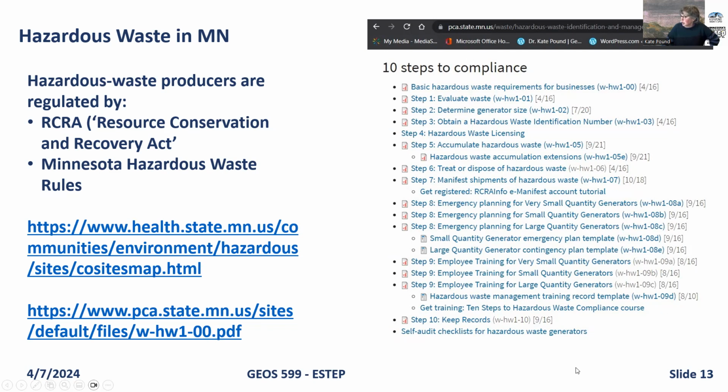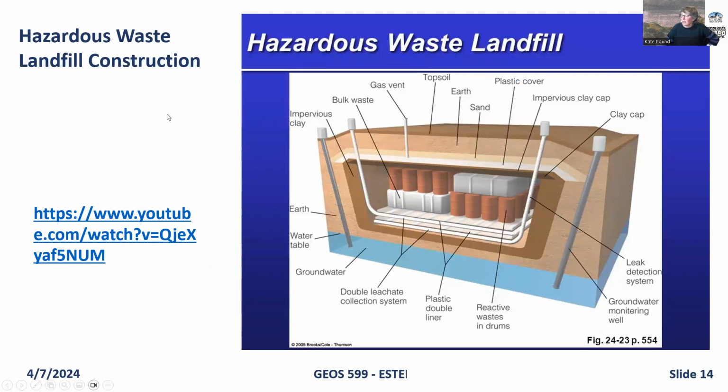I put this image on the right up here so that you just get an appreciation of the complexity around the management of hazardous waste. So what ends up being different about a hazardous waste landfill construction? There's a lot of features that are similar. So when you look here, you can see there are gas vents, there are groundwater monitoring wells, but essentially the containment system and the number of liners and the number of leachate collection systems is vastly increased. There's information in the link on the left.